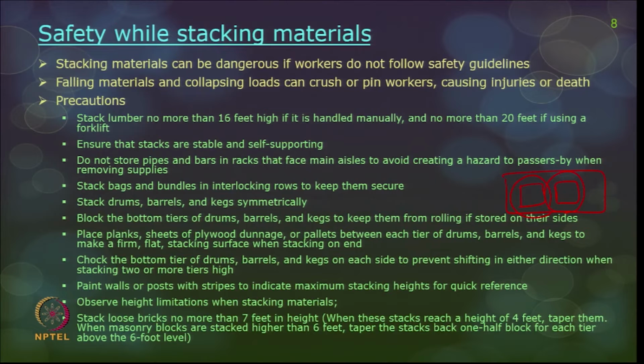And also there are a lot of norms. The stack should not be touching the godown, say the materials godown, on any of the corners, nor leaning on to the roof level or the side walls. All these are not safe when you are stacking cement. These precautions are all available in the IS code. You should have a plank or some elevated support, and start stacking your cement bags on it, so that water or any wet substance does not damage the cement.